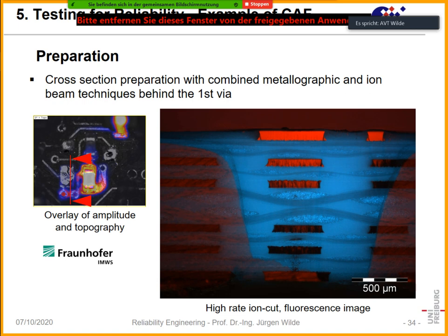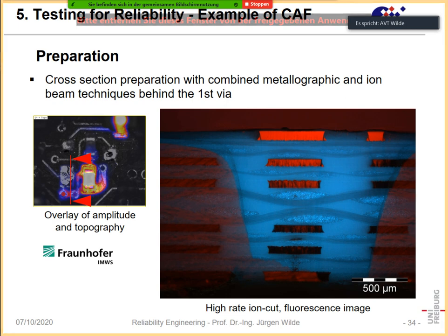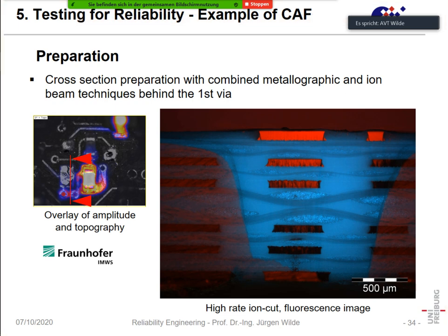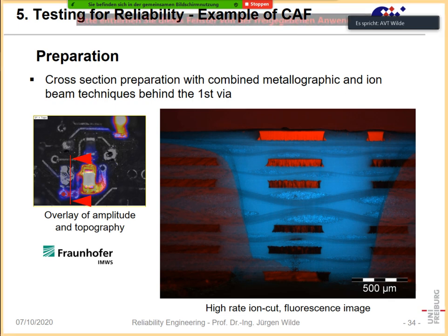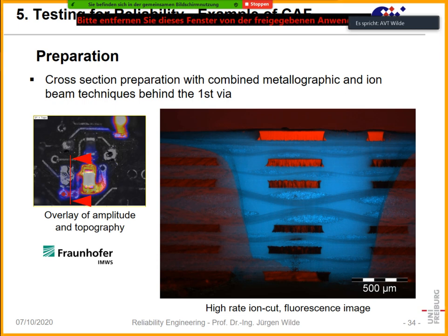Other tricks include using different kinds of light. Here, that was a printed wiring board. Here we can see the glass fibers inside the epoxy. We can see the internal structure of the copper leads. So that was electroplated.